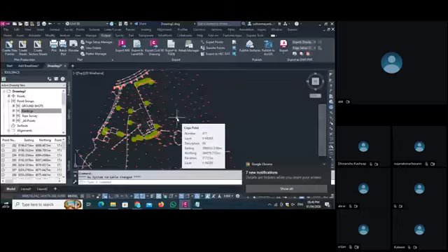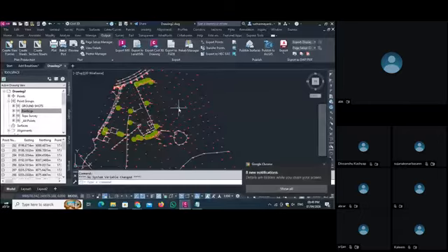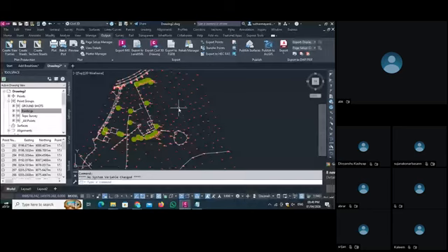So now you understand the COGO point. A COGO point is an intelligent point. You can edit this point from the properties. Also, you can edit this point from the point group. You can change the label style also. For changing the label style, we copy that style. We go in edit and then layout, and then in the layout bar we go to text and change the content, whatever content we need, we can create that style.